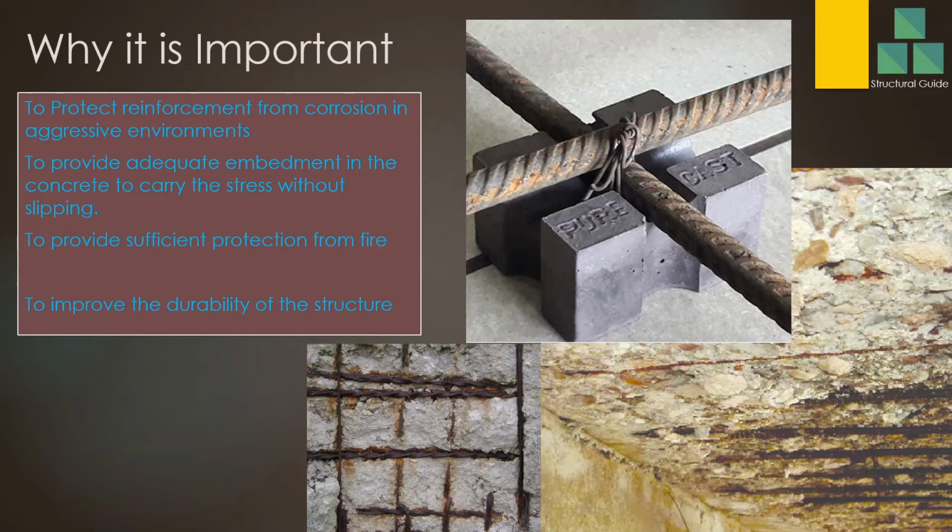During the design, based on the fire rating, we specify the cover. So with a 1 hour fire rating, 2 hour fire rating, or 1.5 hour, depending on that we select the cover to the reinforcement, and we have to consider that in the designs. From all those factors, one of the most important is the durability of the structure, the first point I discussed. We have to maintain the durability of the structure based on the exposure conditions and select the cover accordingly. Selecting a correct cover in a structure is very important.